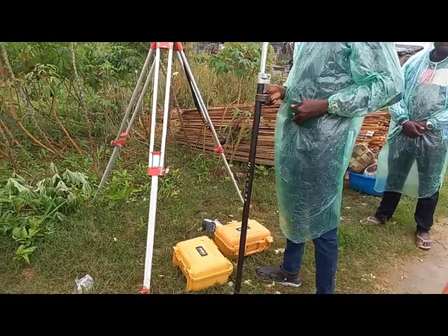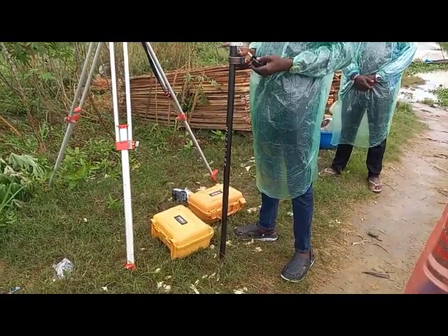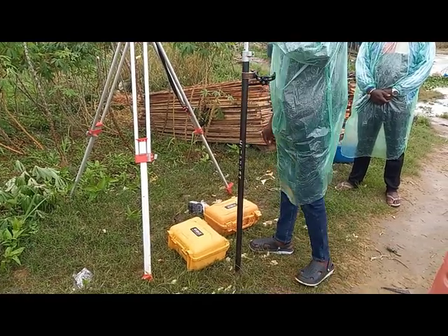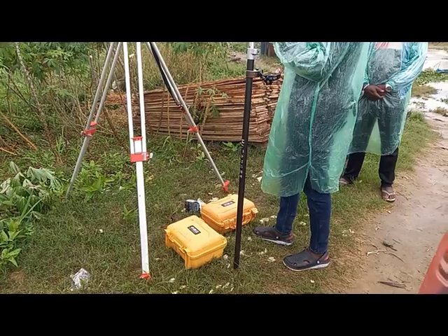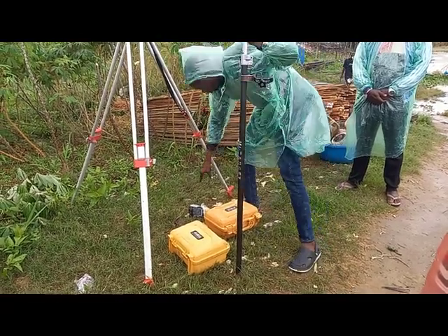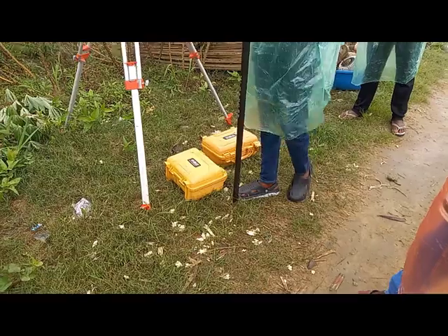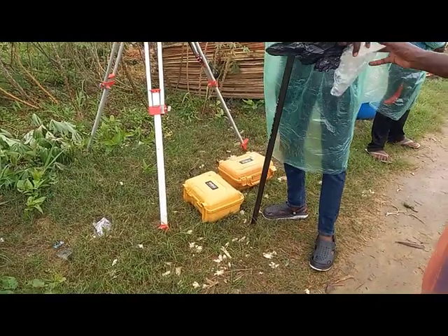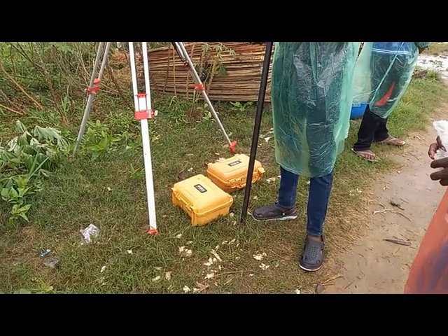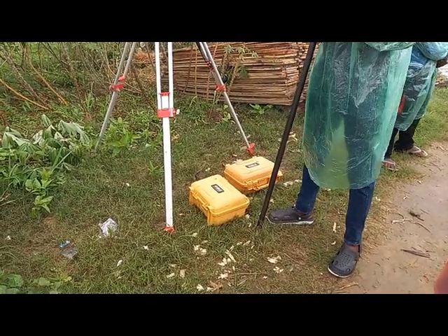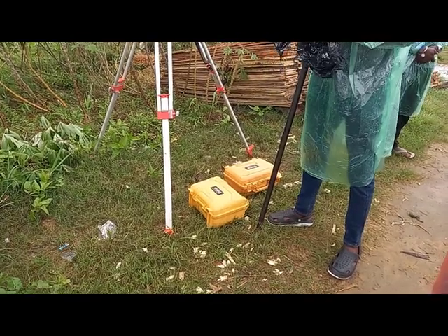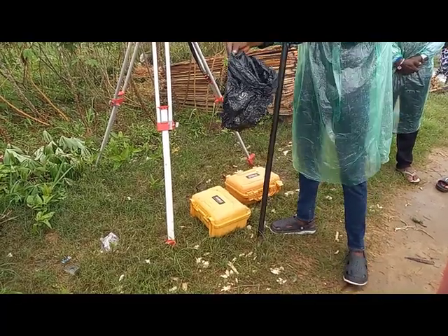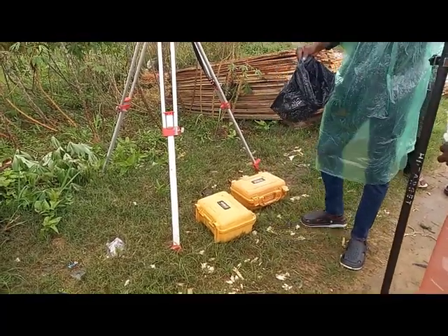So for example, if you have a generally flat terrain, it's easier for you to pick up data at much larger distances, let's say 10 meters or more. But in terrains where you have, for example, a rough and mountainous terrain, you may want to take your points at closely spaced distances. So it depends on the standard that you are following, which needs to be checked properly before you commence.